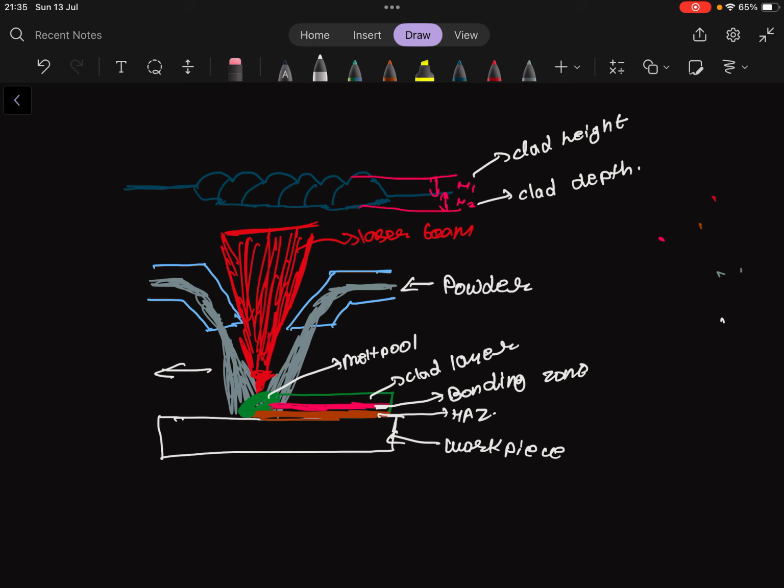In laser cladding we have powder flow, which is sprayed at the surface of a component through nozzles and melted by the laser beam. So we have localized melting of the powder on the surface of our component. This means that once the powders reach the surface, they are melted and rapidly cooled down to room temperature.